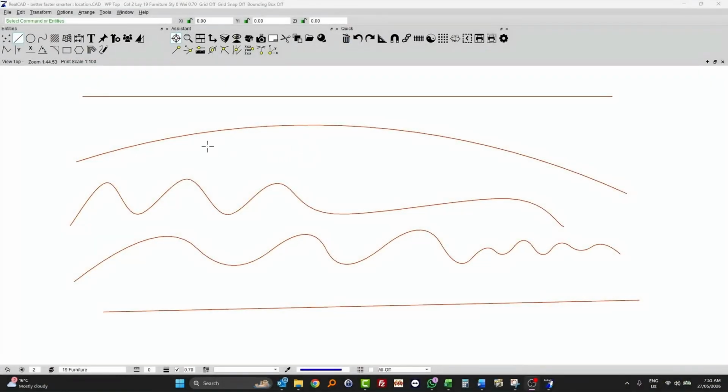In this video, we're going to look at the concept of using the along option, so basically locating along an object. So I'll select locate along. I'm in the middle of drawing a line, and I can type in a distance. So if I type in something like 1000, and I select OK, the prompt will then ask me to select the reference entity.